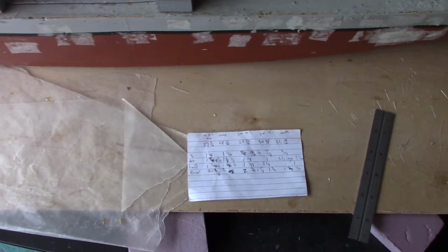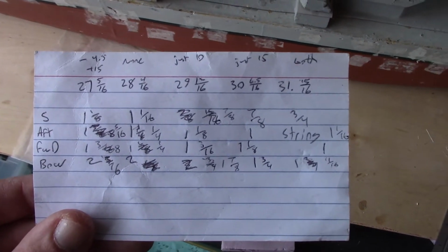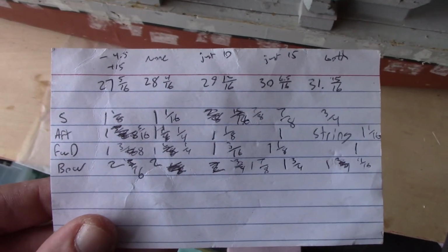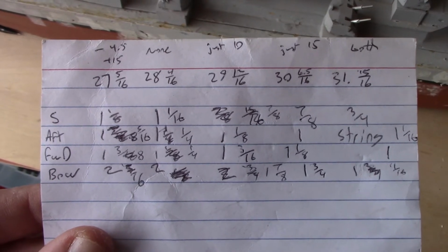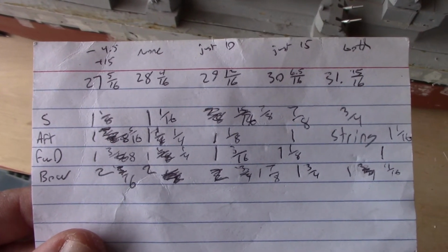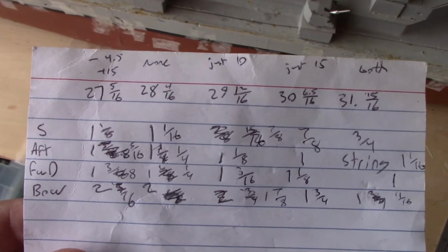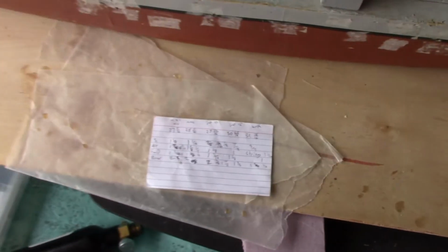of the windows. So now I'm going to talk about how to figure out what waterline I want to use and what freeboard I want to use, which goes back to the float test we did before. So here I have the data sheet that I took from the float test. Unfortunately, it's all scribbled because I ended up doing the float test twice, because the first time I did it, it was dark out and I didn't do a good job. So you can see those different numbers there. The question is, how do you know what's right? How do you know which one to choose?